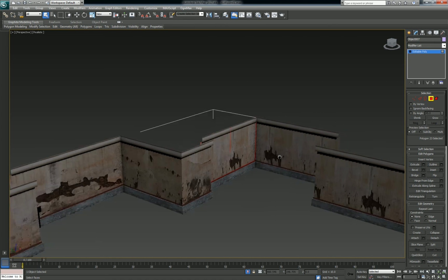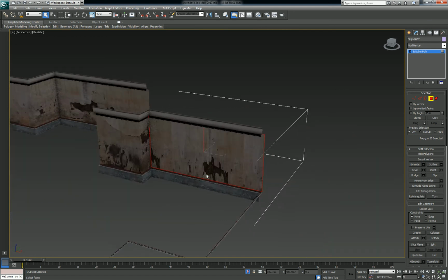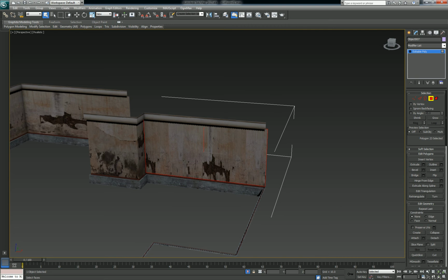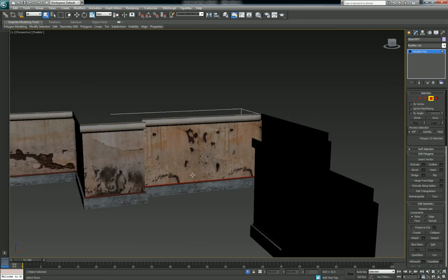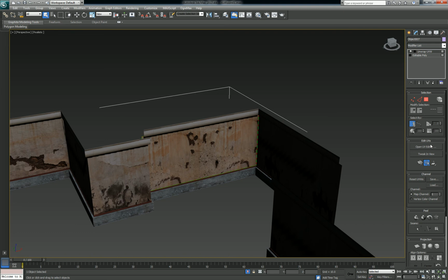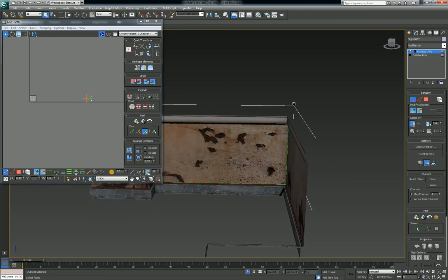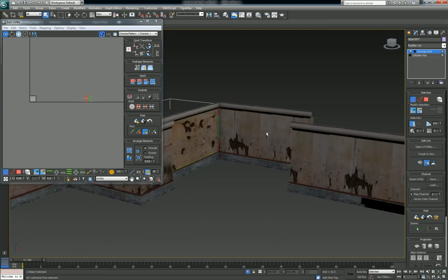There's probably an easier way to do UV map. I probably could work the stack, leave the edit poly modifier, just work up and down. But I find this one here, just doing a wash and rinse, keeps things kind of safe and orderly. Doing things within a process like this, you can't really go wrong. It's almost foolproof rather than jumping up and down the stack. I'm pretty sure somebody would say different, but yeah.